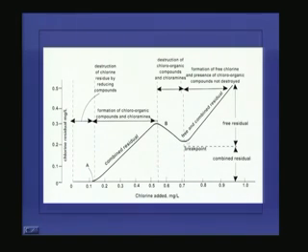If we further add chlorine, this is the free and combined residual chlorine. From the origin up to this point, that is the combined residual chlorine. From here to here gives you the free residual chlorine, and this is the breakpoint chlorine. So this breakpoint is very, very important. If you want to find out the disinfectant concentration required, we have to prepare this breakpoint curve, add chlorine up to this breakpoint, and add a little more to maintain the residual chlorine prescribed by the standards.